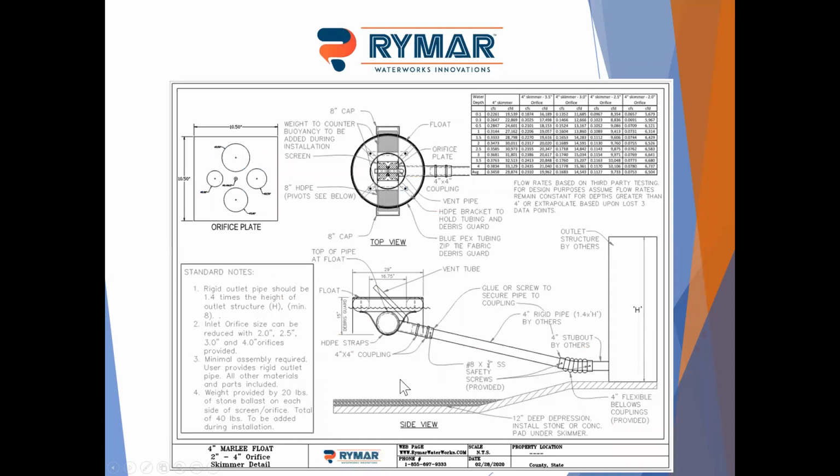A couple of things about our detail. I mentioned earlier the orifice plate when we had the question about the orifice sizes. So this is our 4-inch skimmer. Our 2, 3, and 4 come with one plate like this. By default, this is a 4-inch skimmer, but you use this plate. If you zoom in here, you'll see that's a 3.5, 3, 2.5, and 2-inch orifice. That simply goes inside the skimmer, and I'll show you a video here in just a second how that works.